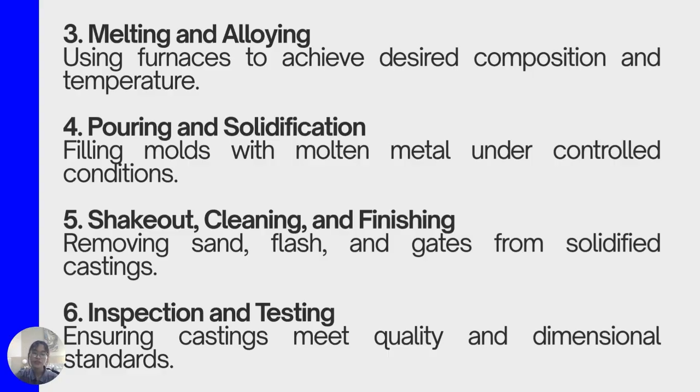There is also foundry automation, which includes CAD and CAM systems for precise pattern and mold designs, robotics for pouring, handling, and cleaning castings, sensors and monitoring systems for temperature and process control, automated inspection systems for real-time defect detection, and Industry 4.0 integration linking all equipment for data-driven process optimization. Automation in foundries leads to higher efficiency, consistent product quality, improved worker safety, and reduced material waste. The modern foundry is evolving into a smart, interconnected manufacturing environment that combines craftsmanship with advanced technology.